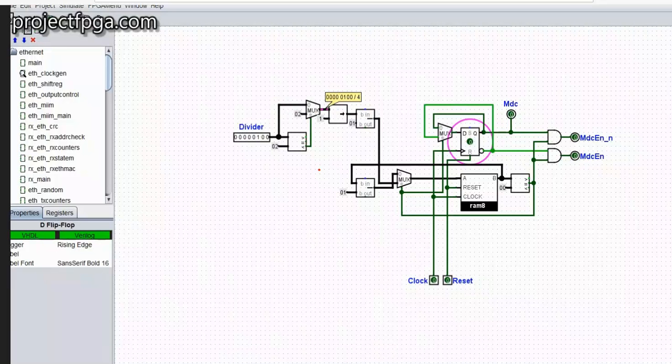So when this value is being shifted by 1, it means it has been divided by 2, and dividing a value that is less than 2 by 2 won't give you a real number. So that is the essence of this comparison, comparing the divider with the value 2. Once you've shifted it, the new value is now being fed to this multiplexer.